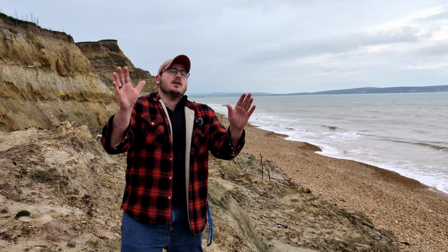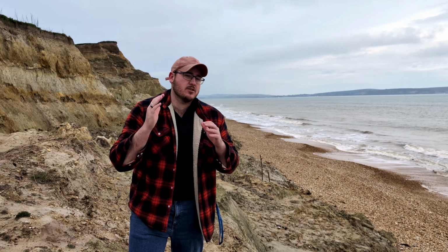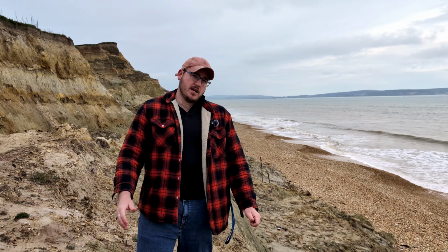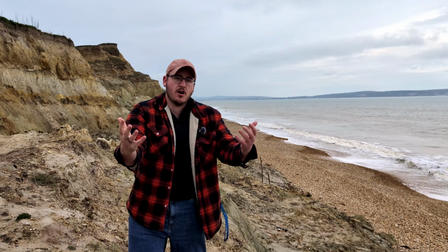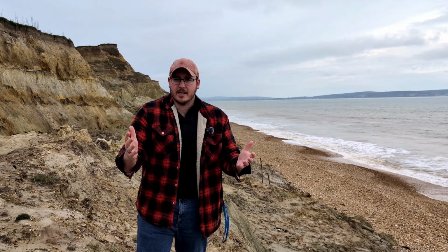Now, the important caveat to mention here is the fact we're not using ground control points, so accuracy in terms of absolutes is not our goal. That will come down the line when we have enough money to actually get ourselves a GPS and we can start exploring more of the survey-related modeling missions that we're going to try and do. But for now, that's the goal. And at the end of it, we should be able to produce a pretty cool little ortho. So let's just get flying.